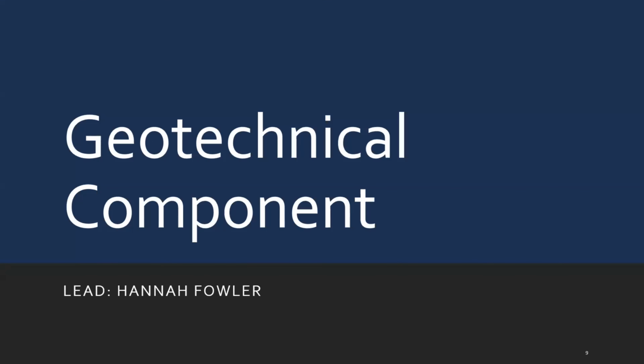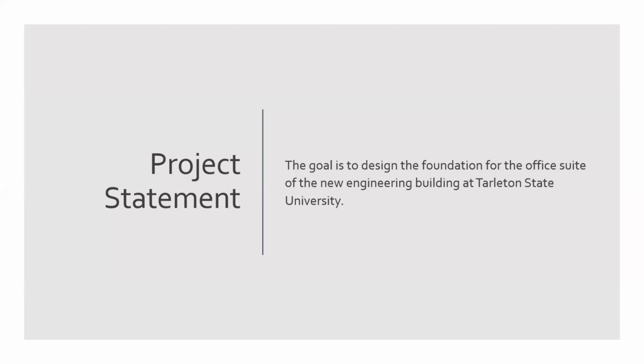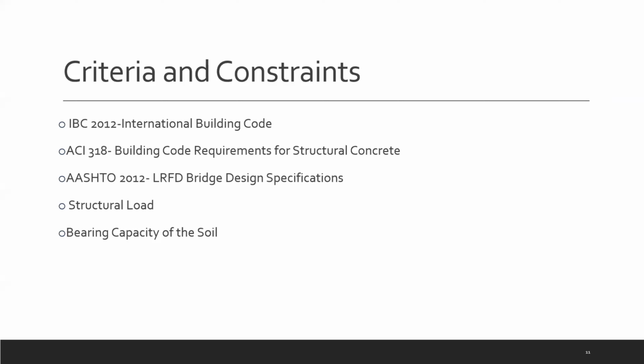Thank you, Dylan. As I said before, I am the project lead for the geotechnical components of our project. The goal of the geotechnical portion is to design the foundation for the office suite of the new engineering building at Tarleton State University. To ensure that the foundation meets the design standards, these 3 manuals will be used. Some of the constraints of the foundation are the structural load and the bearing capacity of the soil. This set of criteria determines the type of foundation that can be used.